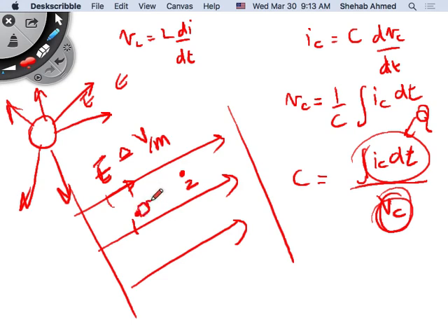Take small areas here, because the strength here is volts per meter. If I multiply by meter, right? If I multiply by that distance, or add up these small distances, all this distance together is basically an integration of this electric field strength, right? So if I do this, then I will get the voltage between 2 points. So if I integrate the electric field strength between these 2 points, then I should be able to calculate the voltage difference.